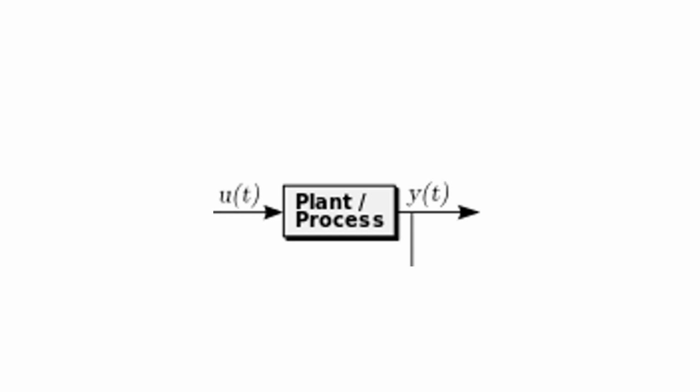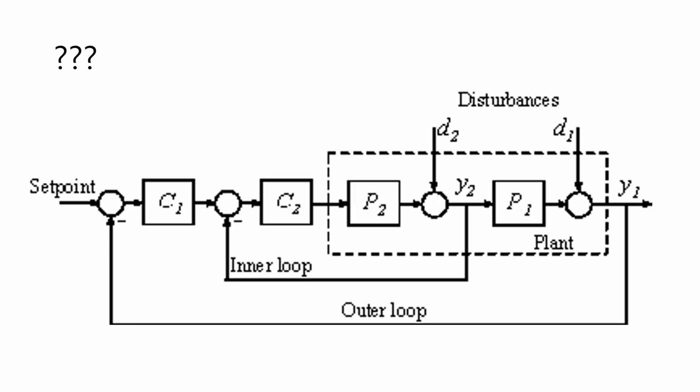And what we have learned so far is that we can improve the performance of open loop systems with closed loop systems. So let's add another PID controller to this open loop. Now we have two PID controllers, with the output of the inner loop affecting the input of the outer loop and the output of the outer loop affecting the input of the inner loop. These PID control loops are cascaded, hence the name Cascade PID control.